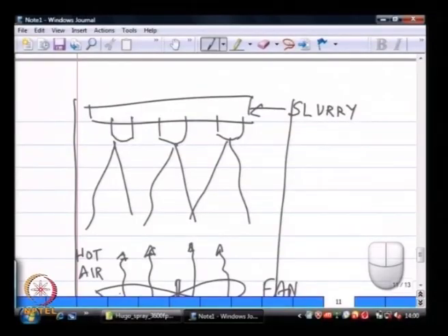So, the point of this is to show you that very often there are conflicting requirements in any design process. In the case of spray drying, these are the conflicting requirements: I do not want drops much smaller than a certain critical size, because they produce product that is not what the customer is used to seeing. On the other hand, if I produce too large a drop, I may get wet product coming out at the bottom of my kiln. So, these two extremes essentially dictate how a spray dryer design works, and this is the basic principle of operation.